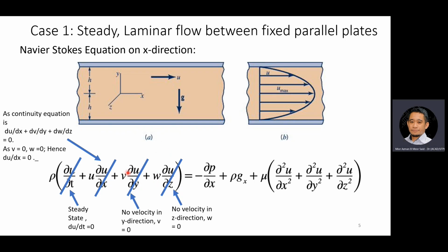So it's easy for us because we've gotten rid of the non-linear terms and the time-dependent terms. This becomes 0, and on this side we can solve it, right? Also, u does not change with respect to the z direction. We also know that there's no gravity in the x direction, only gravity in the y direction. So this term is equal to 0 as well.